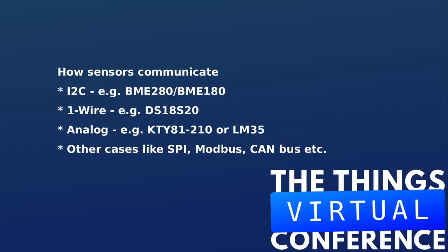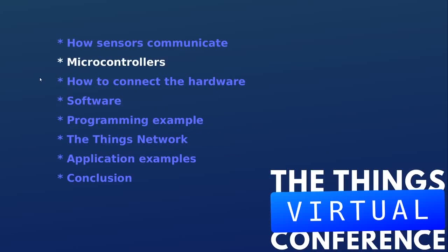A few differences. And with regard to one-wire, we will try out the DS18S20 or DS18B20. There are, again, a couple of different models. They work the same, one-wire actually, and they are temperature sensors. The DS18S20, I have them in two form factors. We will see both. Okay, let's go on to the microcontrollers, as that's what sensors now need.